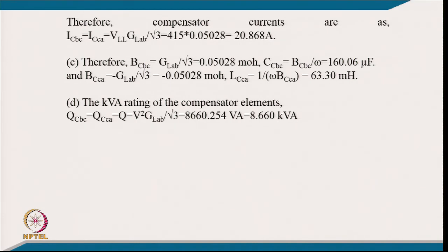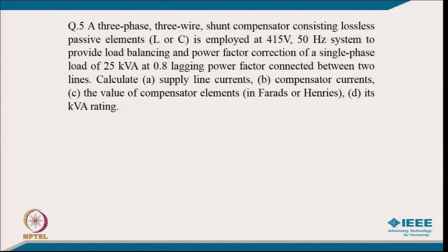So, we have demonstrated how a single line to line resistive load can be made an equivalent balanced sinusoidal unity power factor load using lossless elements, meaning only inductors and capacitors.